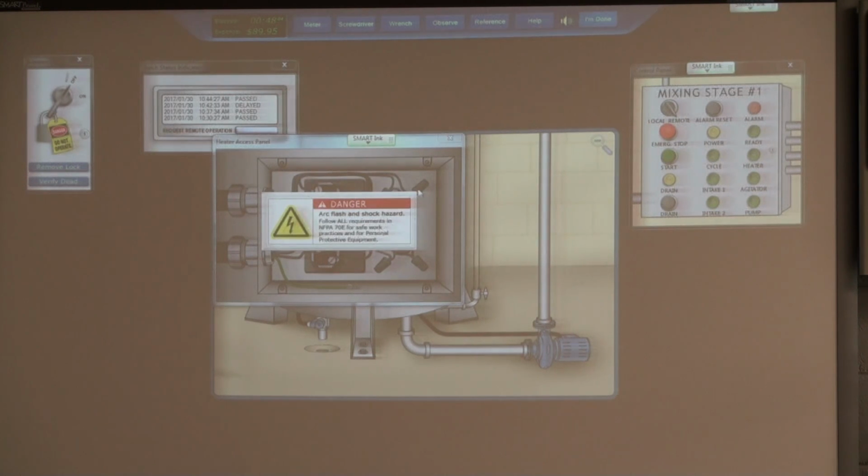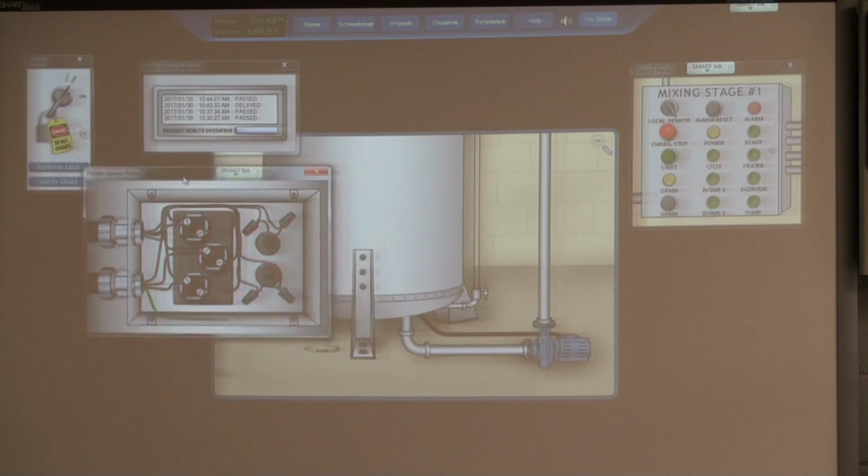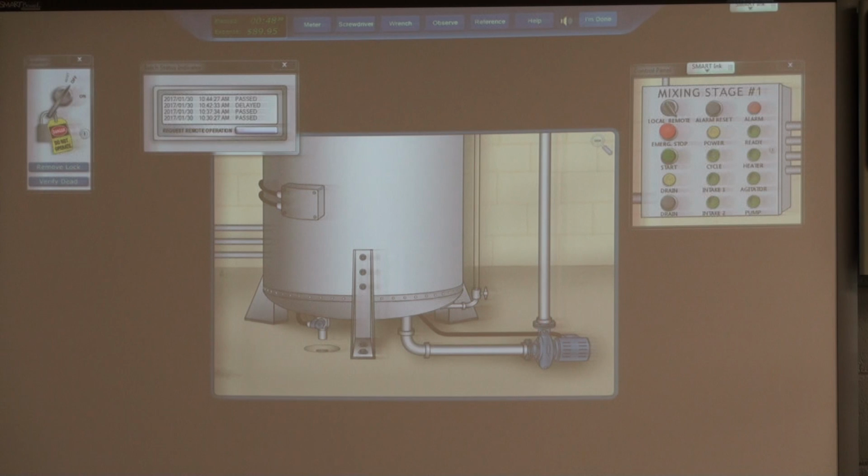Okay. That's your heater coils right there. You can actually ohm them out, you can measure voltages there on the contacts, and so on. So that's the heater cabinet. So basically, where you have electricity running, you can change out that part regardless. So the pump, the valves, it's really about figuring out which components are working and figuring out what's causing it not to work.